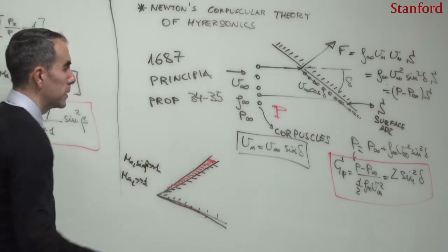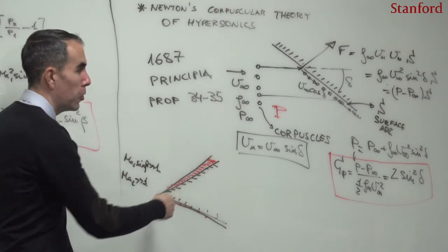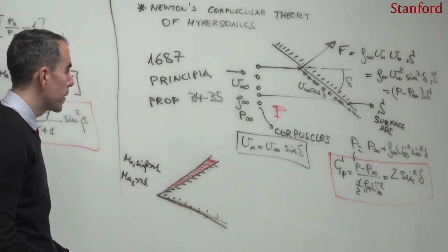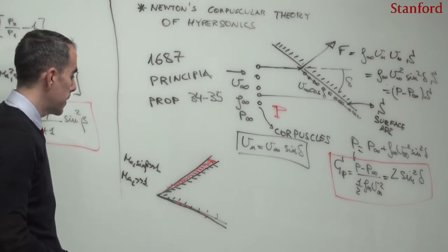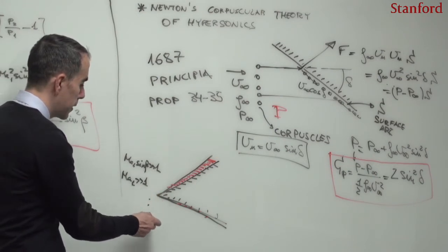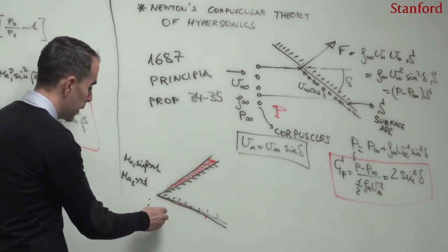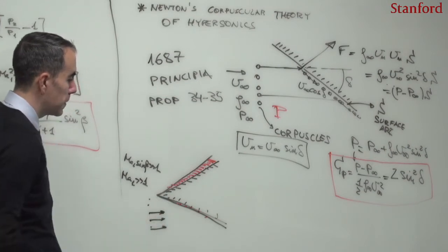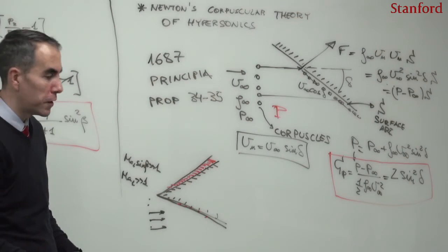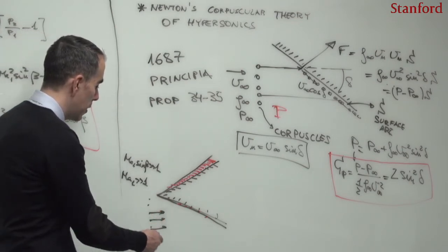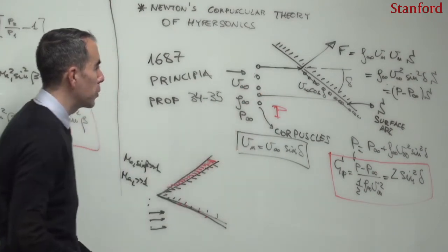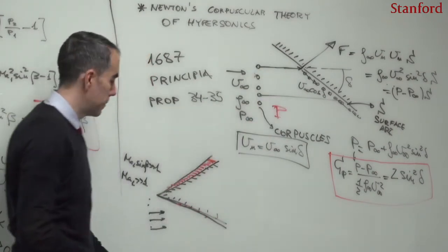Even though in subsonic aerodynamics we know that the fluid is feeling the presence of the body well ahead upstream because of elliptic effects, at hypersonic velocities the molecules of the gas that are moving towards this body don't feel the presence of the body until they are almost close to the surface. So this situation resembles the ballistic collision of the corpuscles in the Newtonian theory.